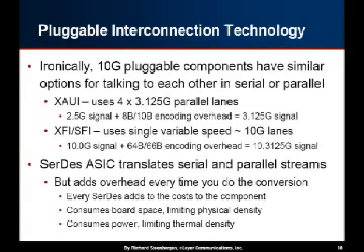And the other major one is XFI, now SFI, which is roughly the same thing, which is a single channel of around 10 gigs. And for example, if you take a 10 gig E signal, it's got a much more efficient encoding method. So your overhead for 10 gig is only a few percent, so 10.3125. And every time you have to do the conversion between these two, it requires a serializer deserializer. And every time you add one of these, it increases the cost of your component, it increases the heat and the power, and consumes board space.